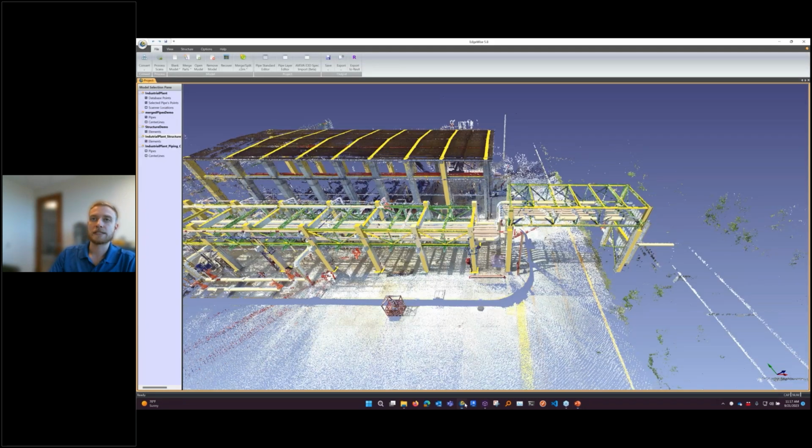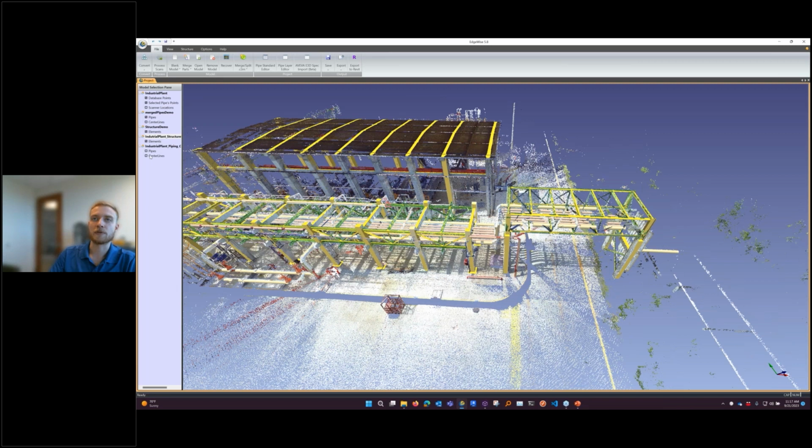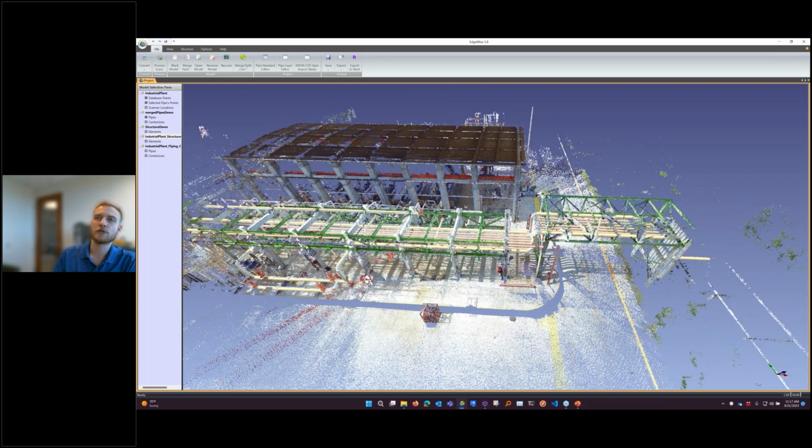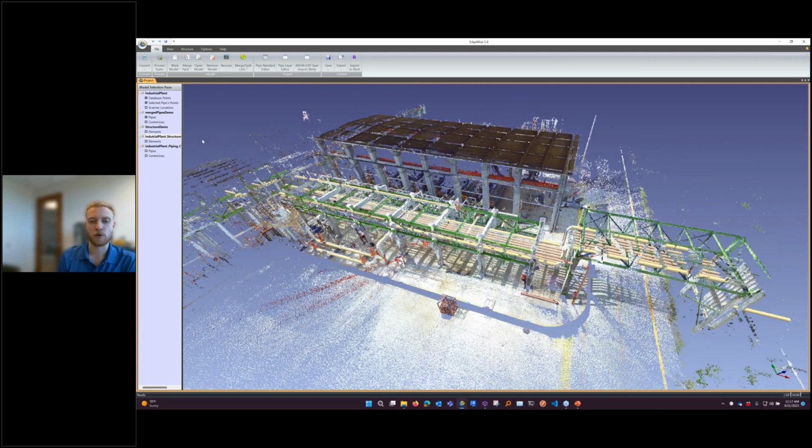So a couple things here that we want to start with taking a look at. The first step when we use EdgeWise is always going to be importing in a point cloud. So this needs to be a registered point cloud that is going through terrestrial. It can be mobile data. It's very flexible. It can be mixed data. It can be unified. It can be terrestrial with all the different scan positions. So it's extremely flexible, but we'll pass in that registered scan data, and we're going to run the EdgeWise process scans